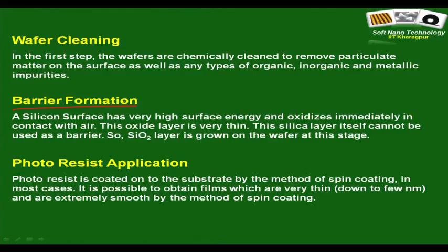You just put it in an oxidizing oven, you adjust the time, how long you would like to keep it, and you can control the thickness of the oxide layer simply by varying the time, because the oxide layer grows vertically in the z direction. So, you simply control the time and maybe the oxygen flow rate. So, once your oxide coated silicon wafer is ready, it is now ready for deposition of the photoresist layer, which